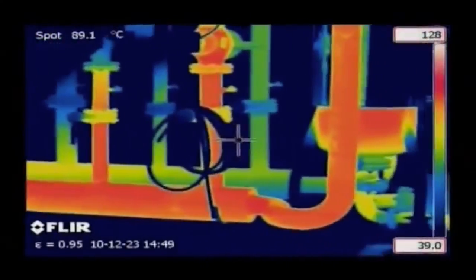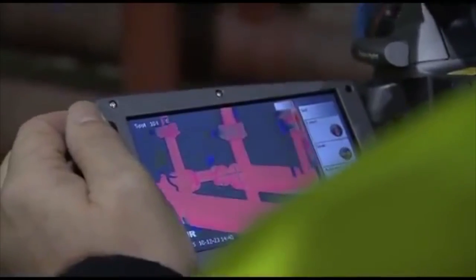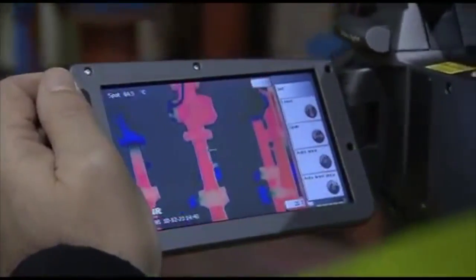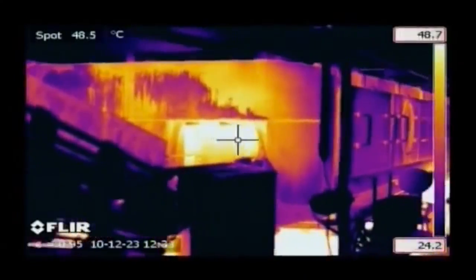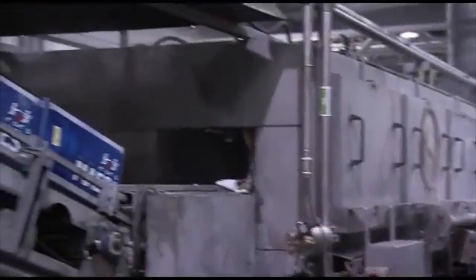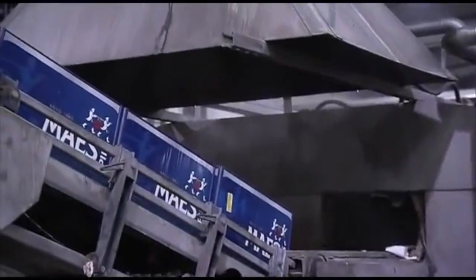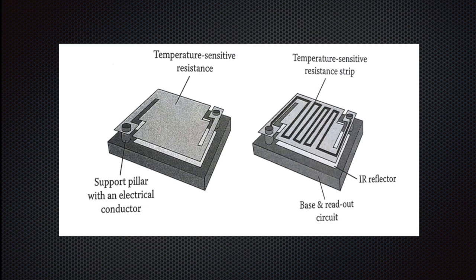Infrared radiation detectors generally fall into two categories: passive infrared detectors that absorb incoming radiation only, and active far-infrared detectors that also emit infrared radiation. Both rely on a detector system that is used to absorb the radiation to heat the detection element, and then use the subsequent temperature rise to trigger a corresponding change in a physical mechanism that can then be measured. One such example is a resistive bolometer array, which runs a wire through a material that experiences a change in resistance when exposed to a change in temperature, then measuring that change in resistance.